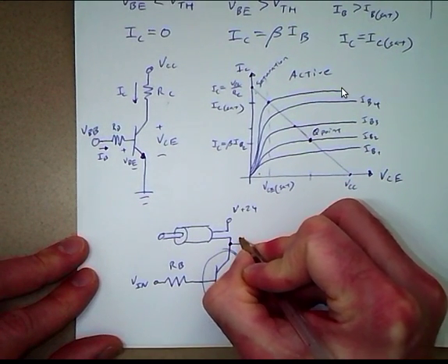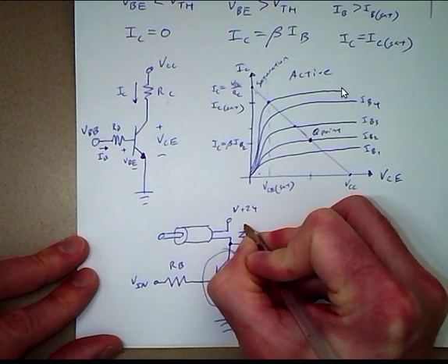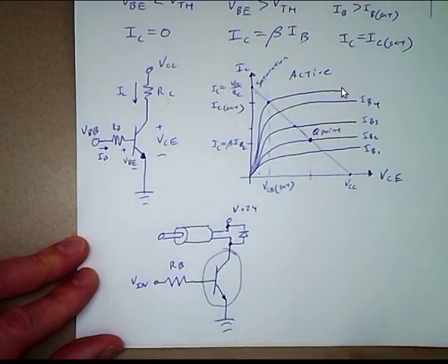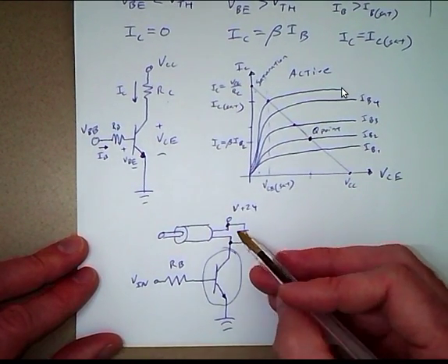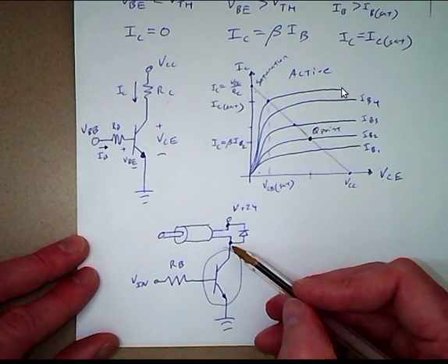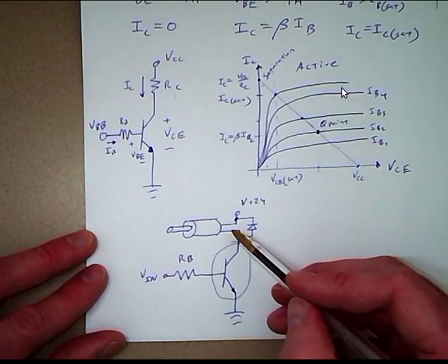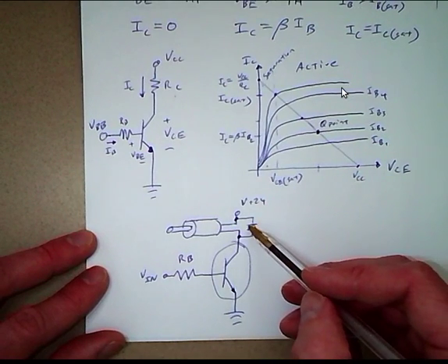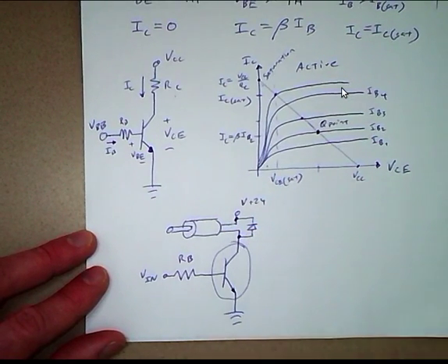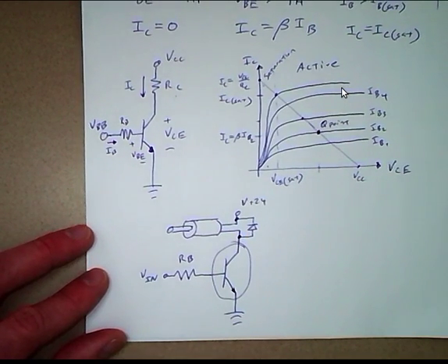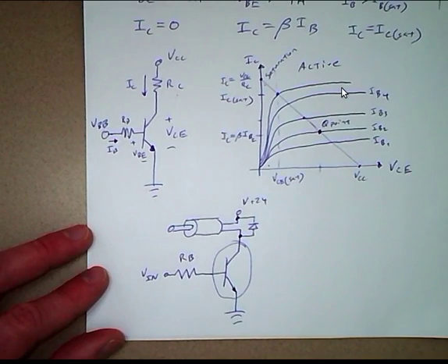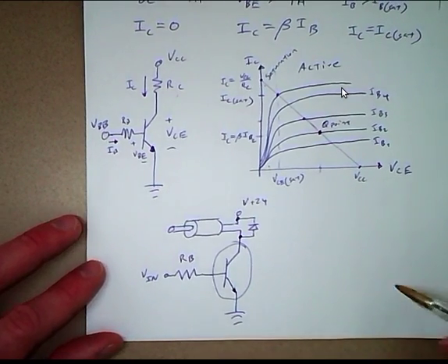So we need our flyback diode. Now whenever we open the switch, there won't be a voltage spike that could destroy our transistor. Instead we allow the energy to dissipate in this circuit right here, in the flyback.